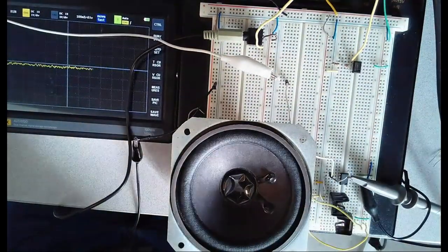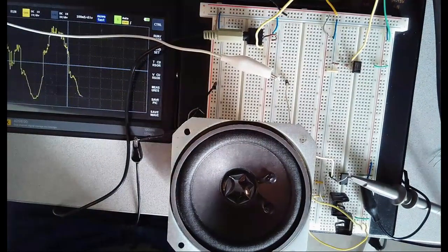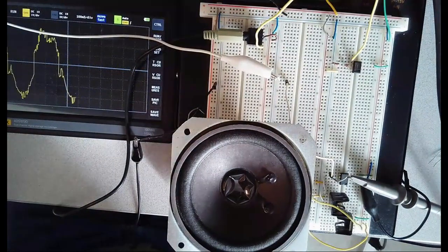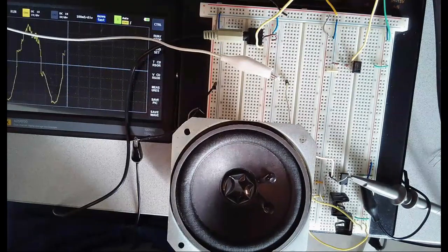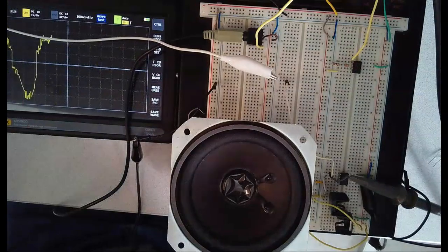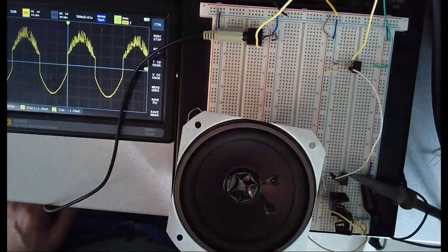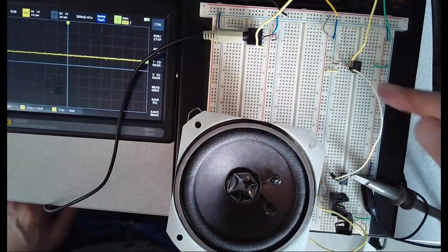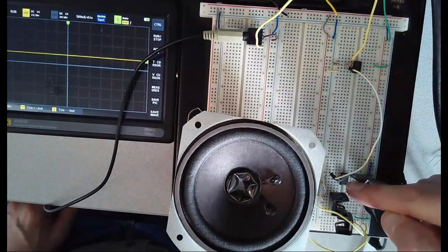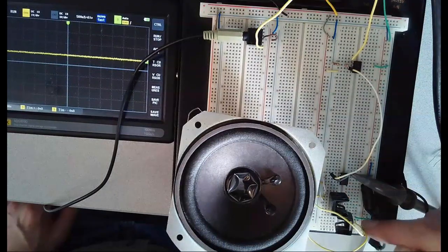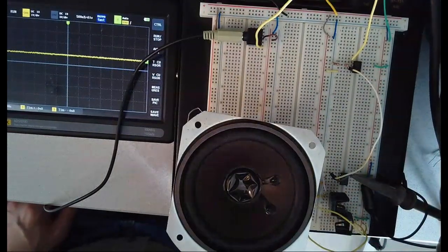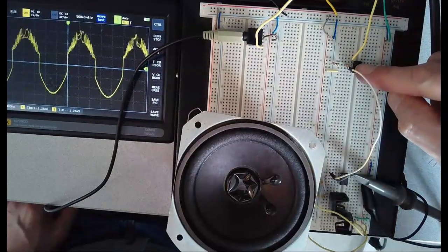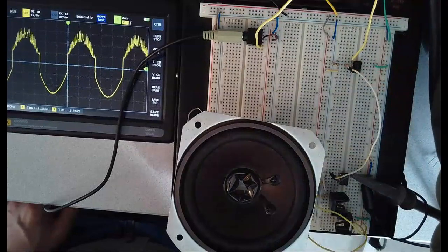And just for fun, this is the voltage at the base. And there's that big jump. That's as I go from push to pull, I have to go from minus 1.4 volts to plus 1.4 volts. Okay, and once you're semi-convinced that the push-pull is working, I can increase the frequency, in this case to 400 Hertz. Kind of annoying. At 400 Hertz, I can measure the gain of the first stage, measure the gain of the push-pull from the input to the speaker. The input to the speaker should be a gain of 1, RMS. And then this guy should be a gain of 4. That's for sine wave input.